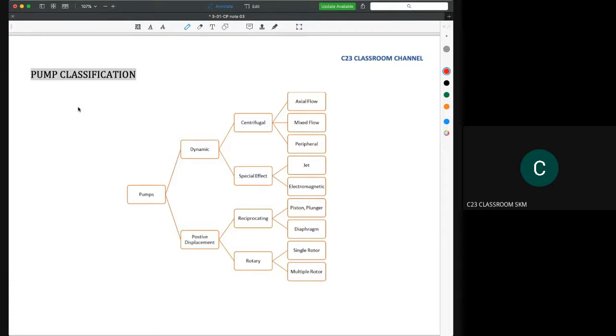You cannot use a centrifugal pump because mayonnaise is not 100% fluid. It is actually a mixture of a lot of ingredients, and we found that the viscosity of mayonnaise is very high, very thick, because mayonnaise cannot flow. So if you have a thicker, or viscous, fluid, you cannot use a centrifugal pump.